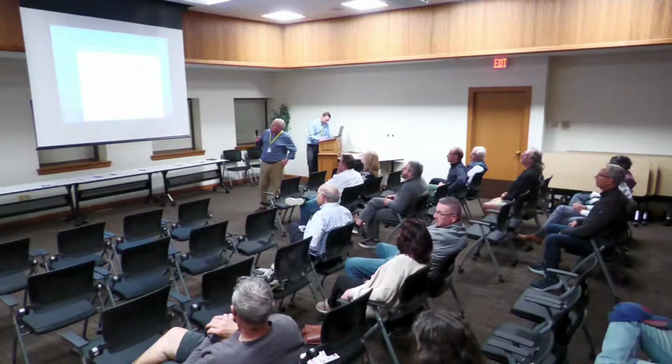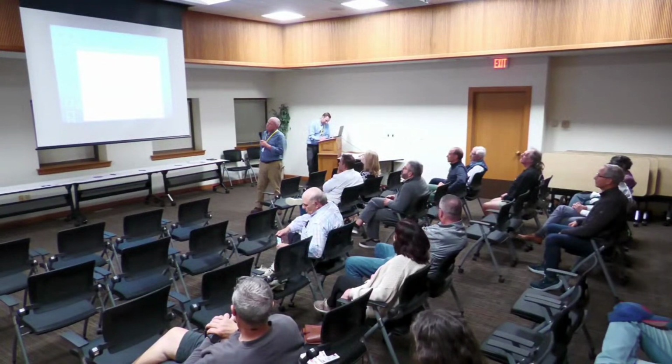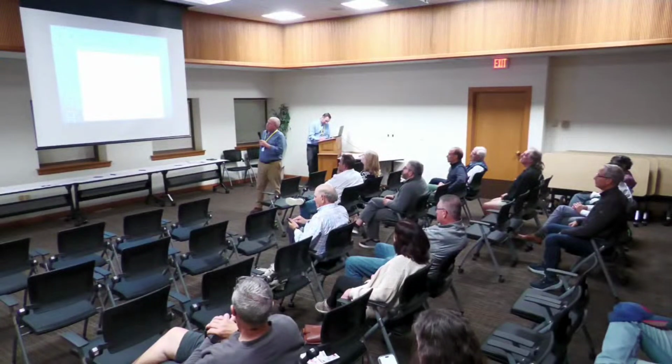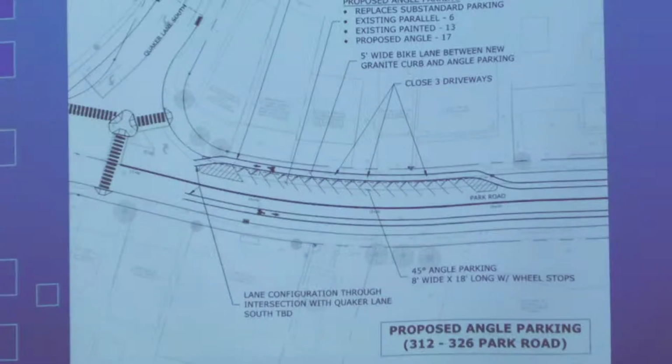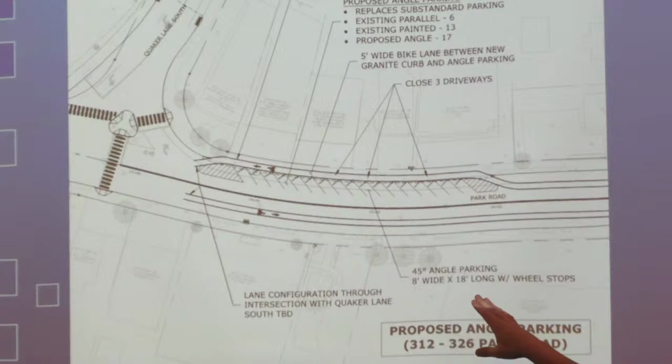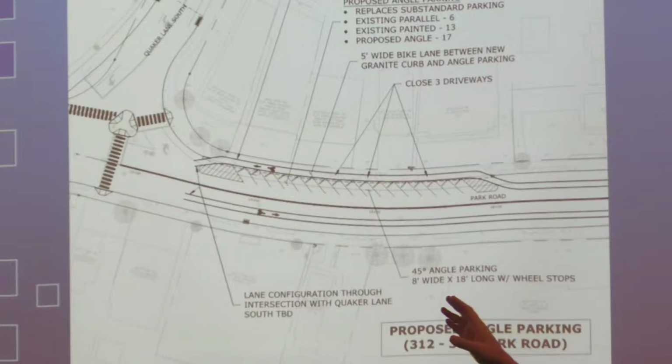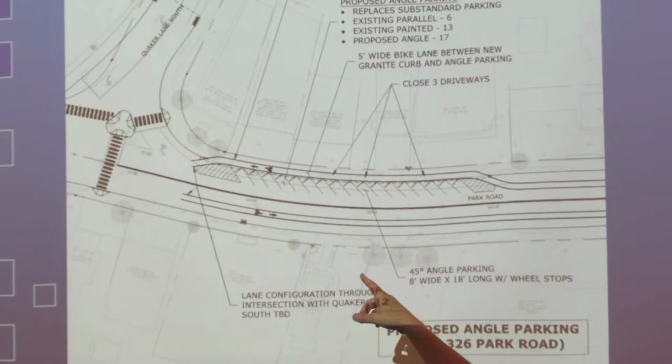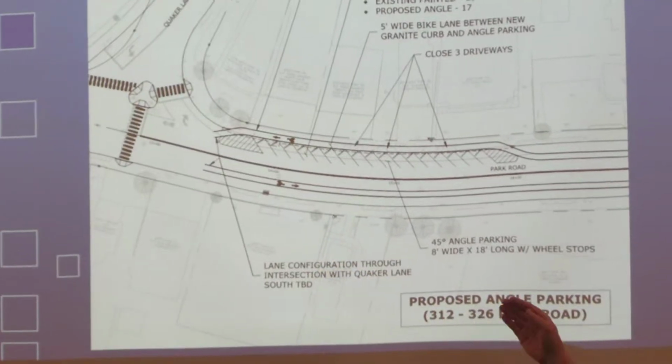With putting the angled parking in, does it reduce the width of the car travel area? Well, we are reducing overall the travel lane down to 10 feet. And then it needs to transition, it's not shown, but it has to transition into that right turn lane. There may be an adjustment, and if we need to, in order to transition that correctly in the best way possible, shorten the parking up a little, that hatched area that's no parking may need to become smaller.